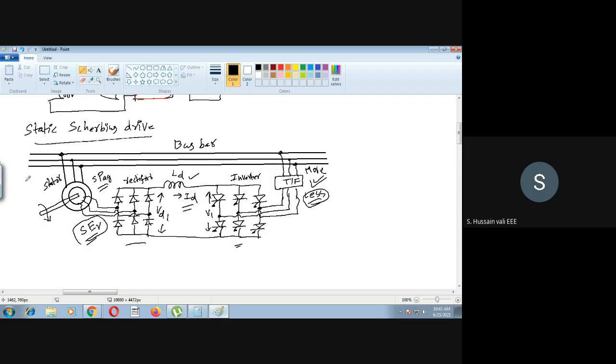See, here you have high voltage, you know very well, because you are giving the supply voltage directly to the stator. What about the rotor voltage? The rotor voltage is less. Why is the rotor voltage less? Because the rotor voltage is proportional to the slip. So as the rotor voltage is less here, because of the presence of the slip, this lesser voltage you rectify, then you do the inversion, and you will also get a lesser voltage only.